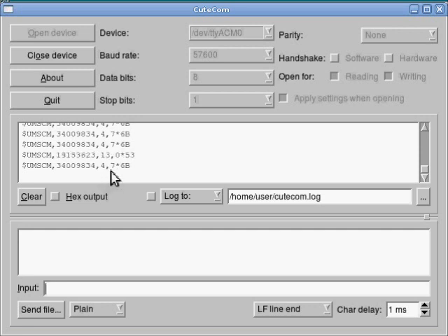The next field is the ERT type. This is a code number that's assigned by Itron for a number of utility meter types. I can tell you the 13 is for certain water meter transmitters, water meter endpoints. In this case, this is coming from an Itron 60W ERT water transmitter.